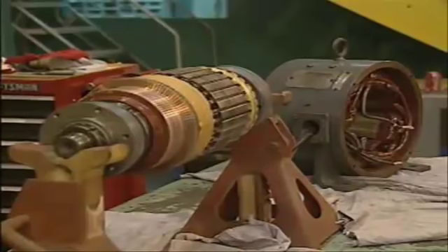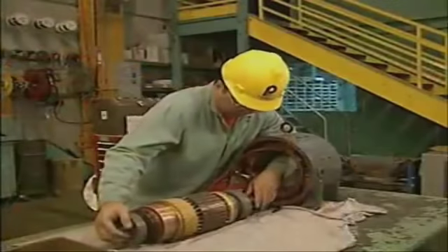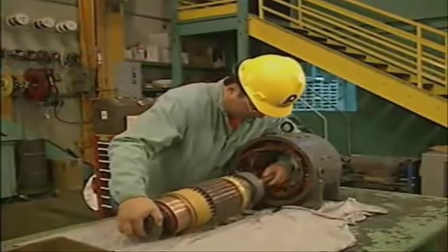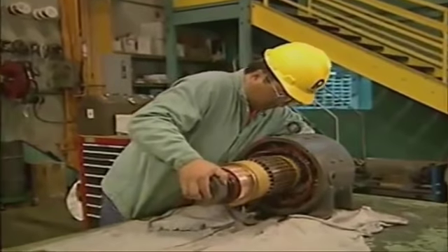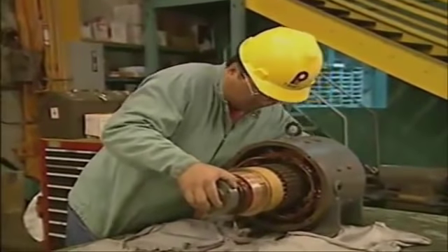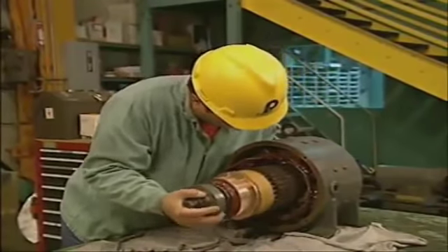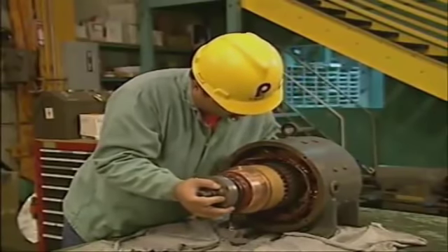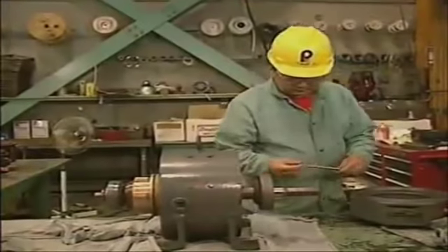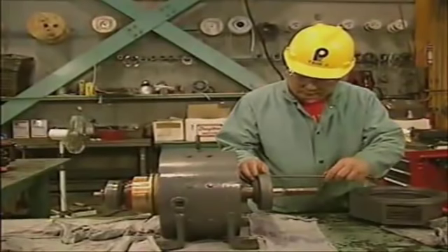In this part, we'll look at how you can reassemble a DC motor after all of its parts have been inspected and cleaned. The first step is to place the armature in the motor frame, being careful not to slide the armature over the pole pieces. The armature should be set so that it rests on the pole pieces. The end bells are then put back in place.